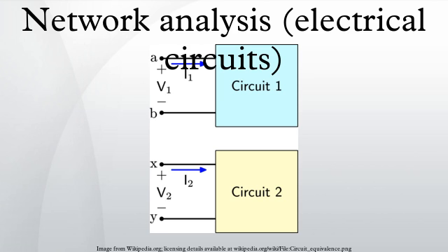General form of network node elimination. The star to delta and series resistor transformations are special cases of the general resistor network node elimination algorithm. Any node connected by resistors R1 to Rn to nodes 1 to n can be replaced by resistors interconnecting the remaining nodes. The resistance between any two nodes is given by the general formula. For a star to delta this reduces to a simpler form. For a series reduction this reduces to another form. For a dangling resistor it results in the elimination of the resistor.